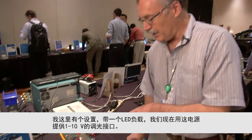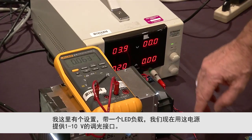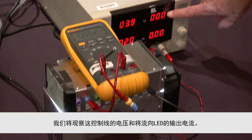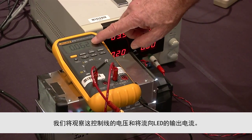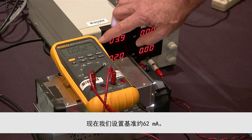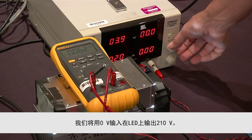I've got a setup here with an LED load, and we're using this power supply to provide the 1 to 10 volt interface for dimming. So we're going to watch the voltage on this control line and the output current that's going to the LED. Right now it's been set up with a baseline of about 62 milliamps. We're running at about 210 volts on the LEDs with 0 volts in.